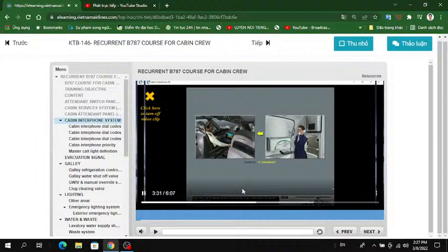Cabin Ready tells the flight deck the cabin is secure and ready for taxi. A chime sounds in the flight deck and a message shows. Pilot-to-attendant calls are enunciated by a chime in the cabin and a master call light. When a pilot-to-attendant call is made, one or two more stations may be added to the connection. Calls from the flight deck take priority over all other calls.